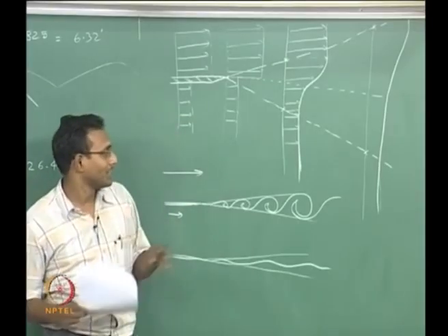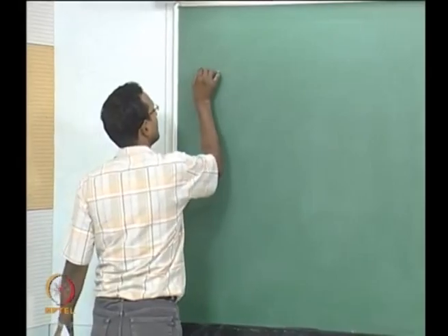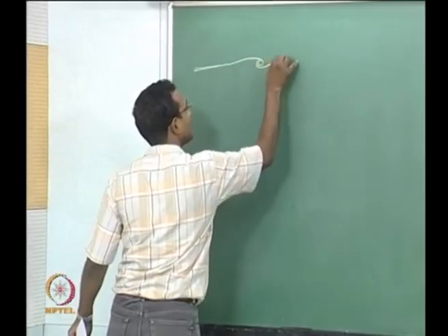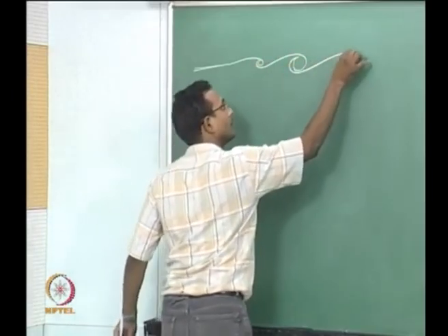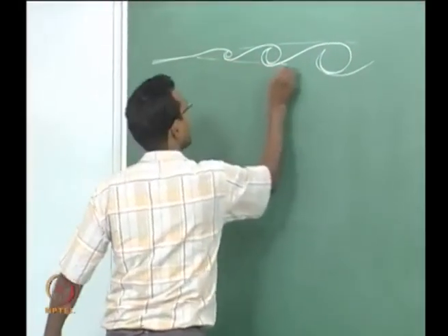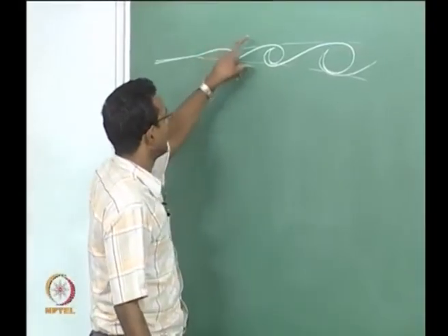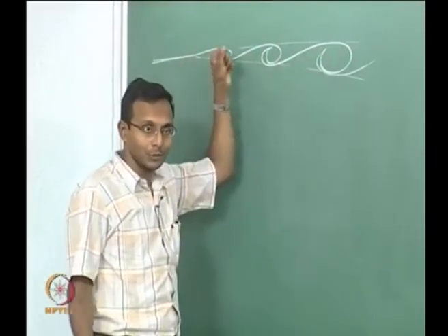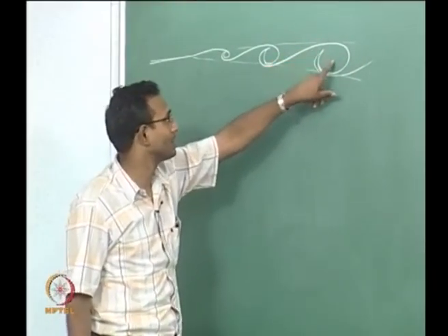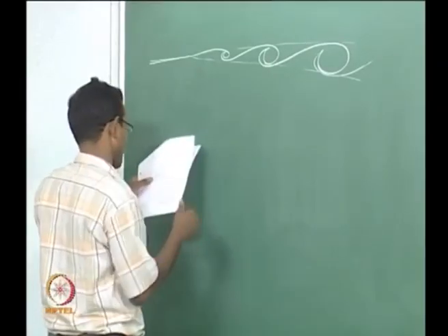Now, people wanted to understand this in compressible shear layers. Something like this, and I am going to say that is my shear layer, and I am saying that it is having some large scale structures that are growing as they go out, and the vorticity strength will keep on decreasing for all of this because it is spreading out more. It is not going to be rotating as fast as the first one.